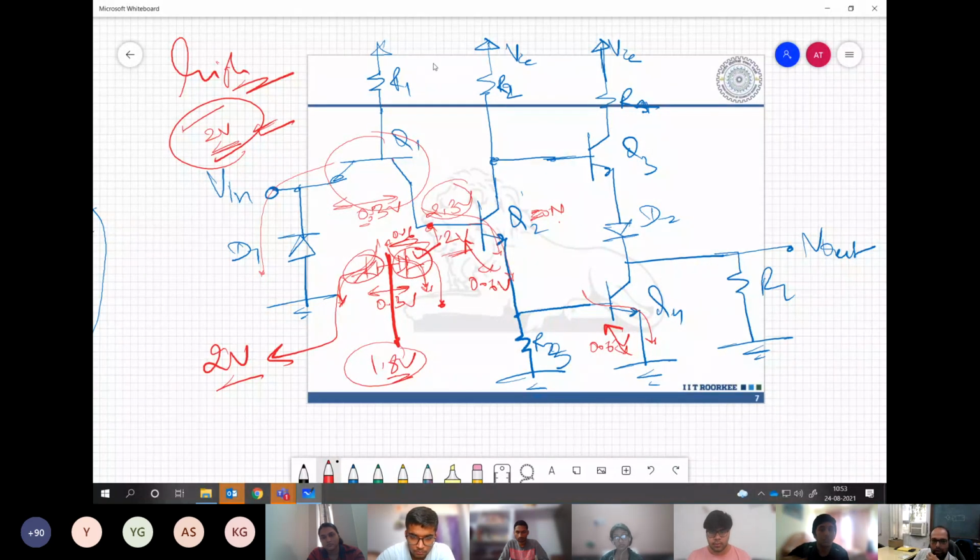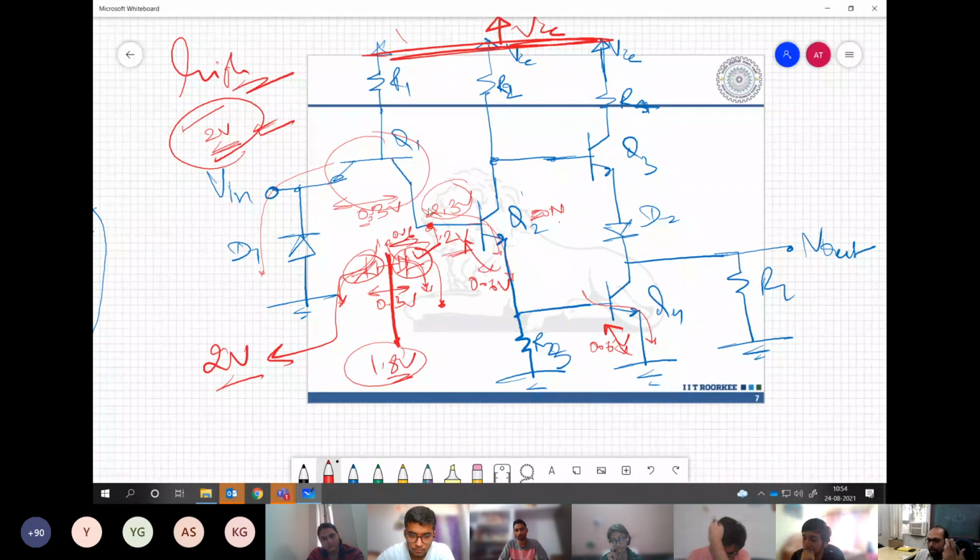So this all is VCC. You can short it together and make it VCC common. So you have to work in this manner. You start from anywhere. Start from a very crude assumption that, okay, this is conducting, fine. Then what will happen next? Once this is conducting, can this conduct? Yes. Can this conduct? Yes. Then can this voltage remain over here as whatever you have assumed?